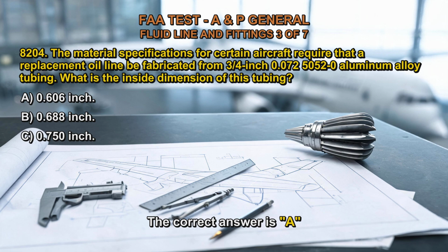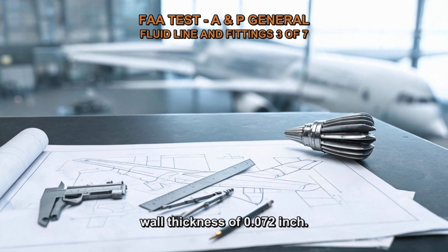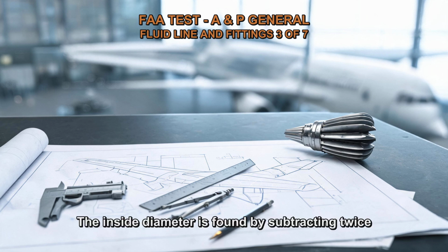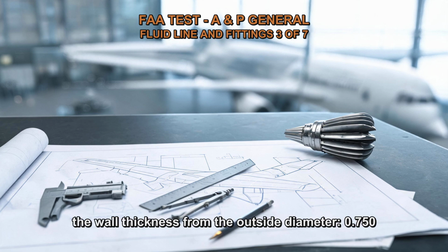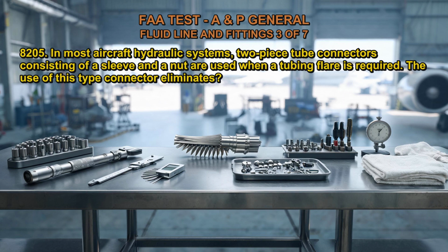The correct answer is A. The tubing has an outside diameter of 3/4 inch, 0.750 inch, and a wall thickness of 0.072 inch. The inside diameter is found by subtracting twice the wall thickness from the outside diameter. 0.750 minus 2 times 0.072 equals 0.606 inch.